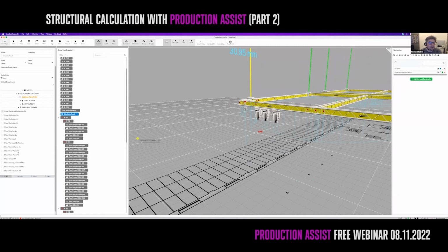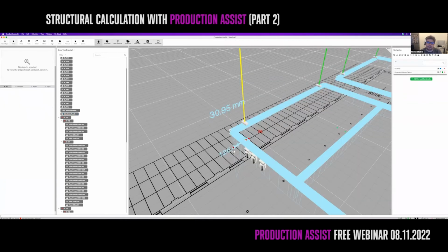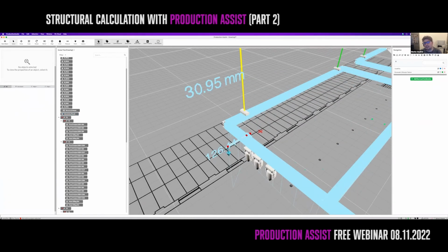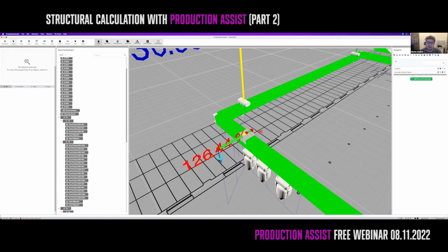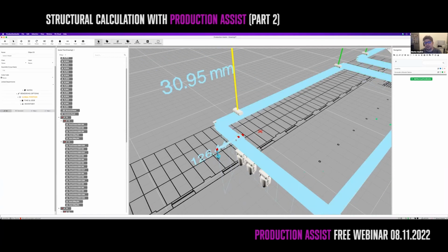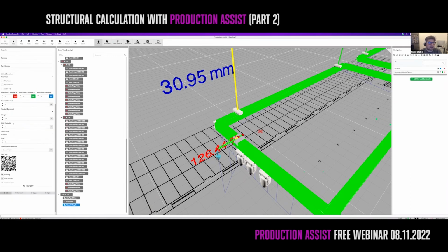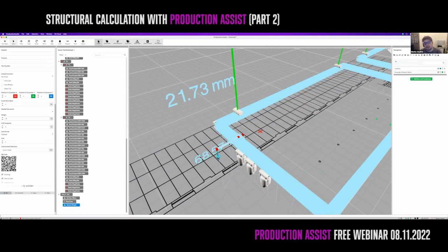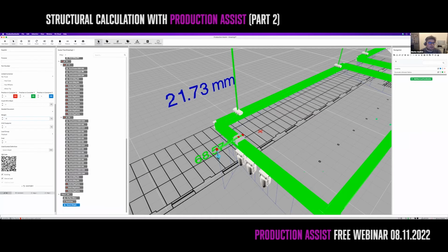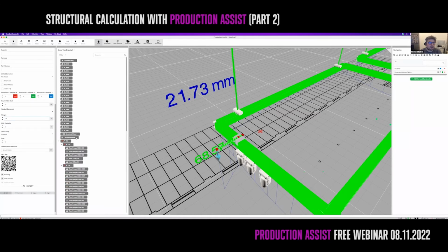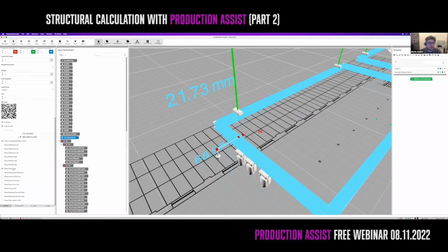Important to know, you also can see if the actual pipe in here is well supported. And you see in here that it's at 130% workload. So putting 50 kilos like this on the truss is really not a good idea. So let me downgrade the load a little bit and say it's only 25 kilograms. You see, that brings it again to 70% workload, which is totally fine for our approaches. So going back to the calculation results and disabling the workload again.